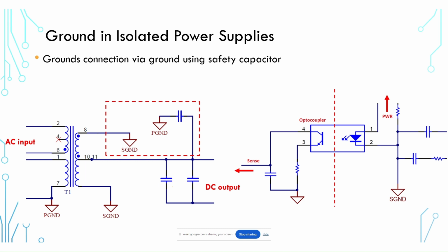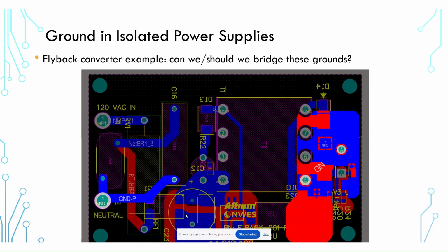Now, what about the size of the Y-type capacitor that is connected here? Well, here you're basically bridging across this transformer, okay? And the whole point of this capacitor is to ensure that noise can travel between these two regions, and you want that noise to travel through that capacitor as a displacement current. Well, in order to do that, you have to ensure that this capacitance is larger than the winding-to-winding capacitance across this transformer. So what is the winding-to-winding capacitance across this transformer?